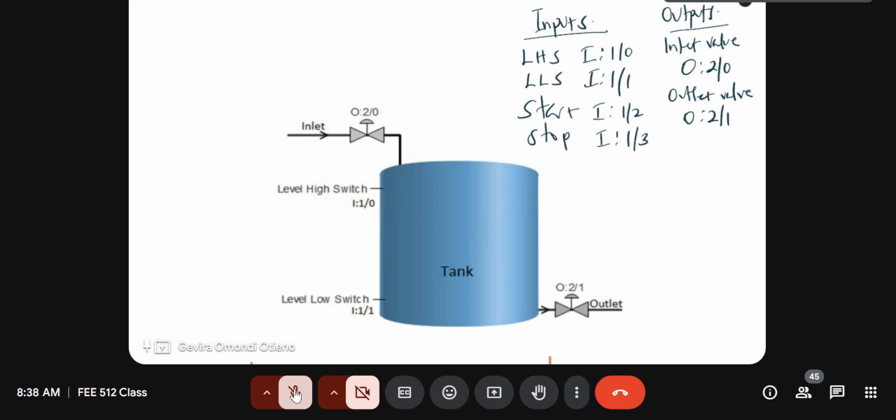needs to work. So for example, now we know we need to detect high and low levels of the liquid in the tank. So we have level switches for that. So the two level switches will now either affect the inlet and the outlet. Okay, so that when there's a high level, we block the inlet, we allow the outlet.